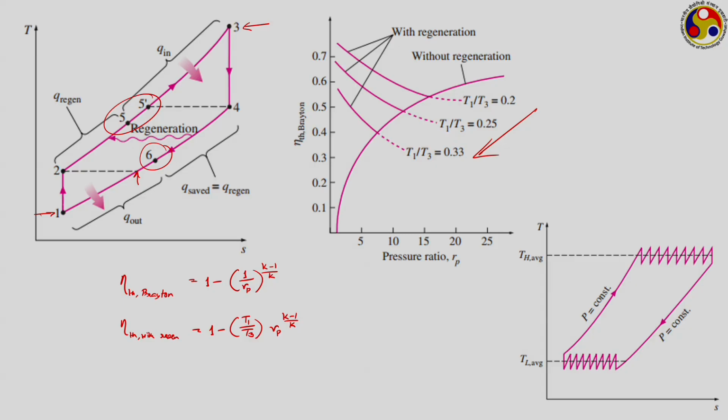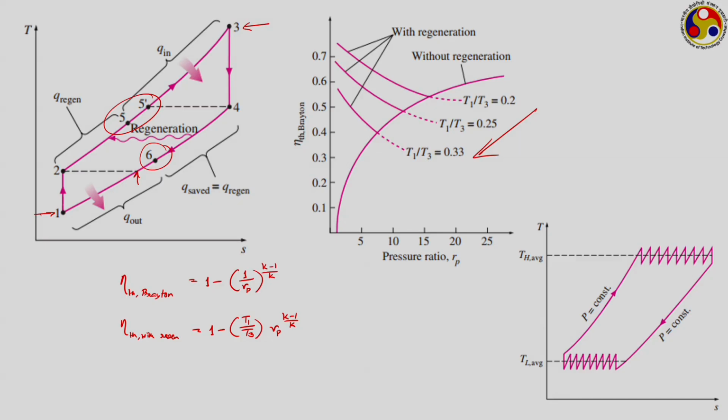As the number of stages of compression and expansion keeps on increasing, we have a scenario something like this. Look at how many stages of compression you can see here. There are so many stages, and each of them has an identical pressure ratio and perfect intercooling in between. Similarly, on the turbine side we have multiple reheaters, each of them having the same pressure ratio, and accordingly we have ideal reheat for this.